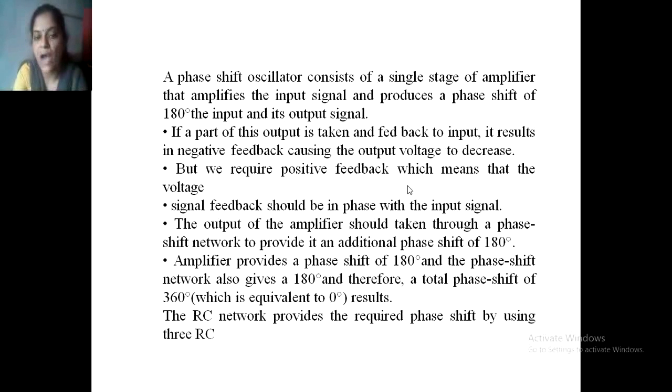So if a part of this output is taken and fed back to the input, it results in negative feedback, causing the output voltage to decrease. But we require positive feedback, which means that the signal feedback should be in phase with the input signal.